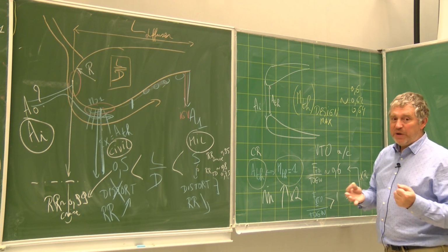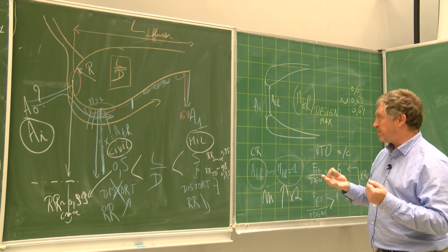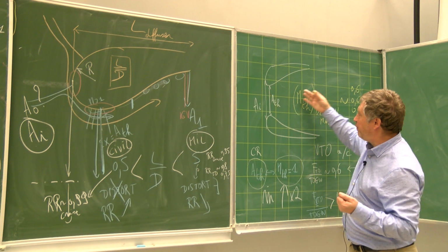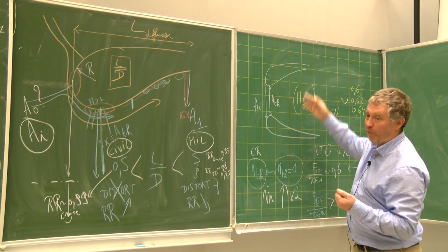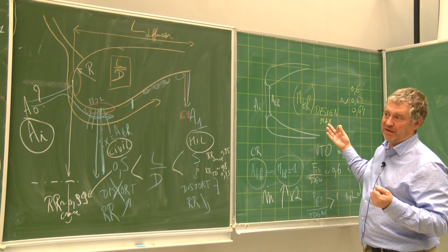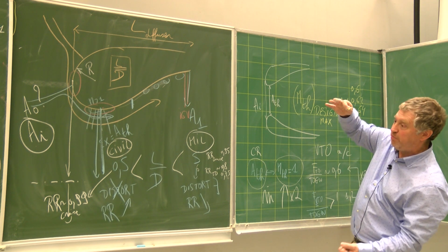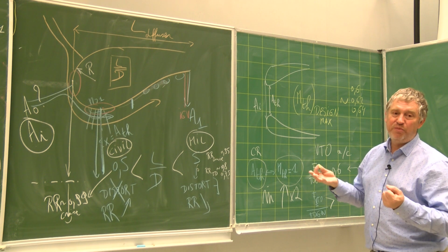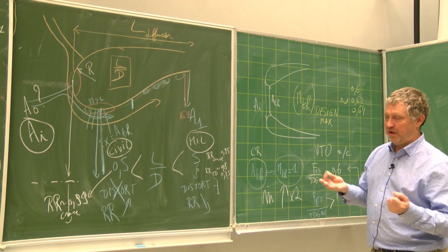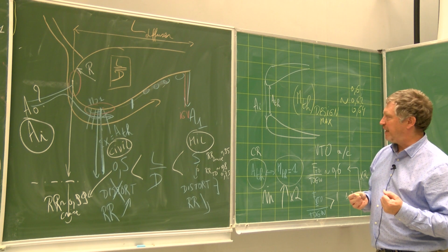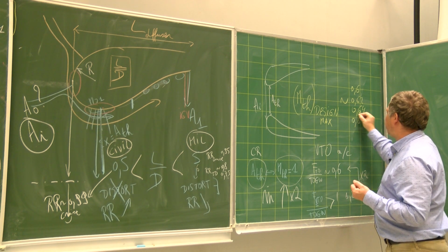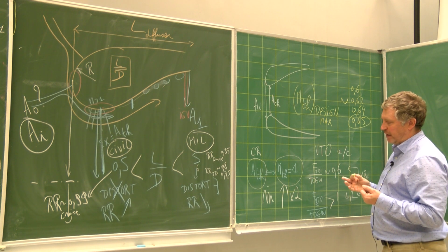Otherwise, we could have problems of being able to have a sufficient flow rate arriving at the level of the compressor. We would have to increase A throat too much, and that would give a too large intake and too much cross-section for the aircraft. So maybe we could be up to 0.65, something like that.